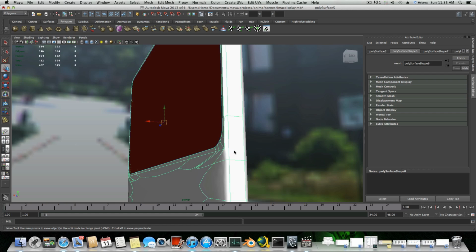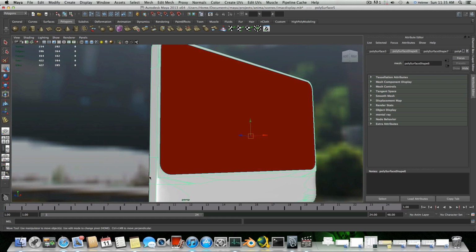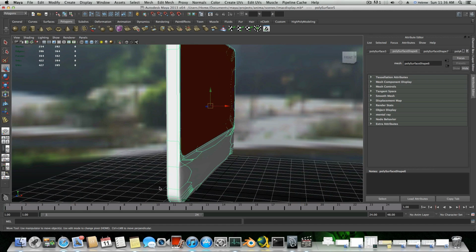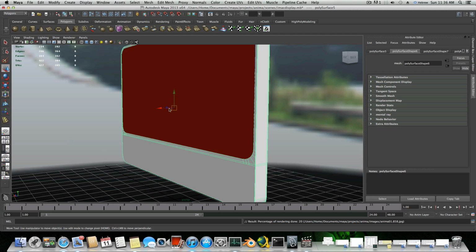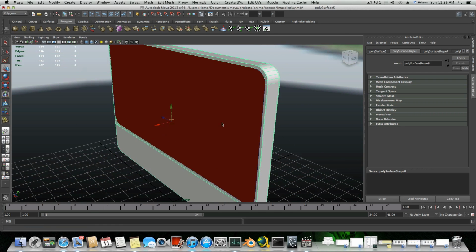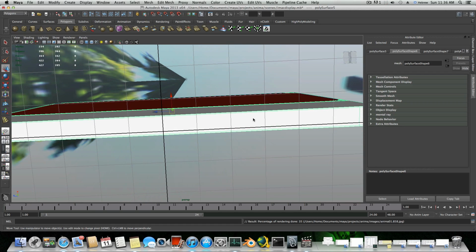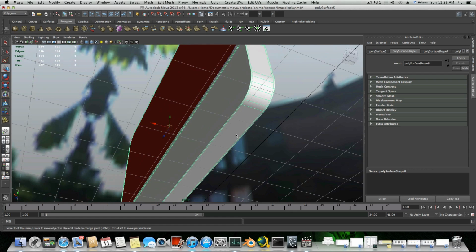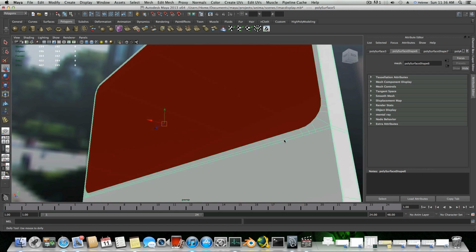Most of them are because some areas here are not connected, like there are no complete edge loops and a few other edges that are supposed to be here. If we are not using smooth preview, that's okay, it doesn't ruin the geometry of our model, but I did want to apply some smooth preview just for the lower part here. I basically want to do it only because I have the grill here. I want the holes to look rounded and smooth and not cubic. So that was the challenge here, and I will show you how I decided to do this.